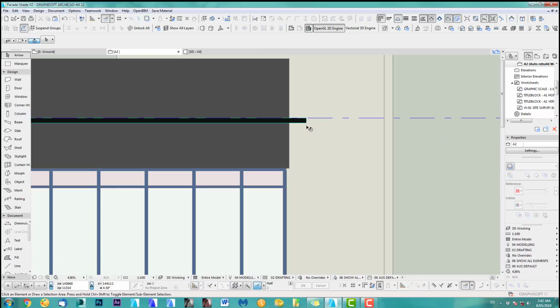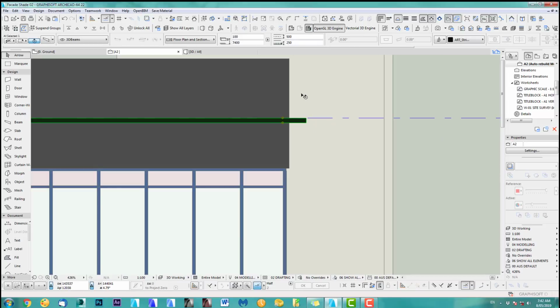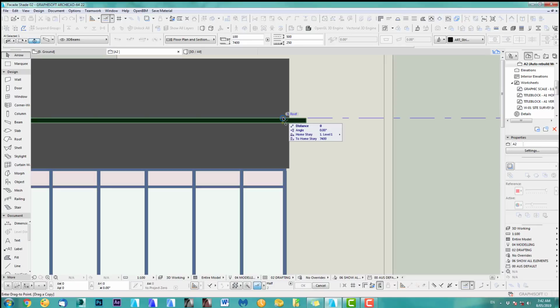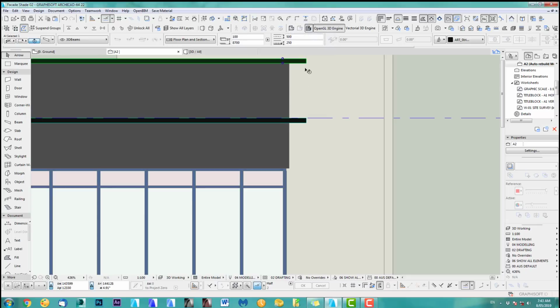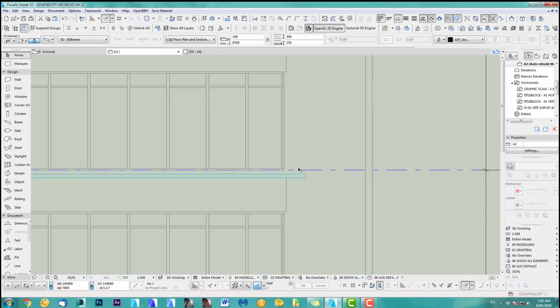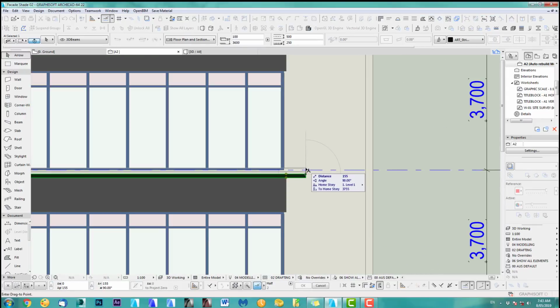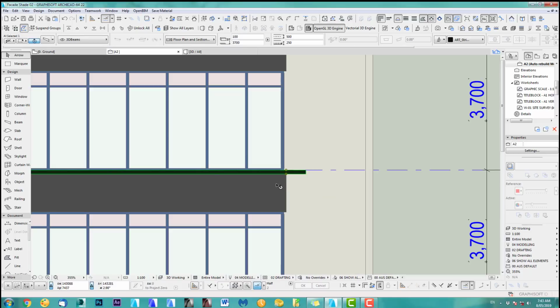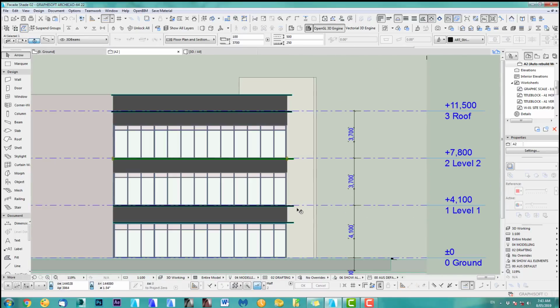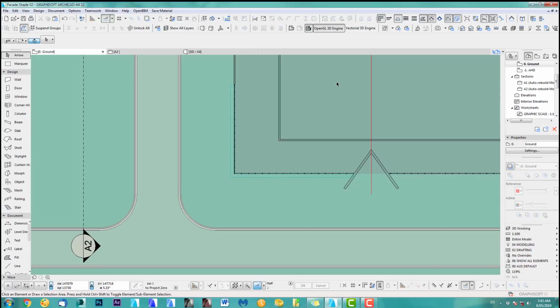Actually, sorry, my mistake, not 1200 down, I want to go 1200 up. So we should be able to drag a copy here, and just move it up and say 1200. Actually I need 1300 because my blade is 100 thick. All right, so I've got 1200 in between, and I can see this one I drew too low. This has to be there. Perfect, otherwise I've got a gap. All right, cool. So this we've got now in 3D.